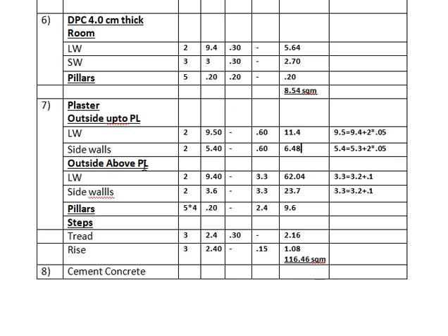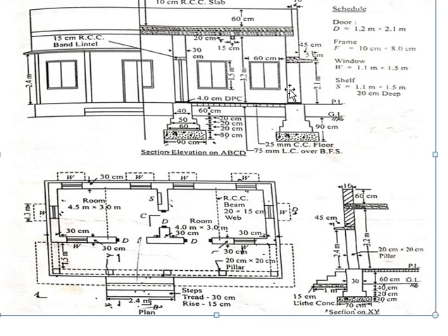Now outside above plinth level, again for the long wall and the side walls. Talking about the length, it will be 9.40. When we are calculating above plinth level, we do not add the offsets, so the length will be 9.40. Total height, you can see the total height is 3.2 meter.